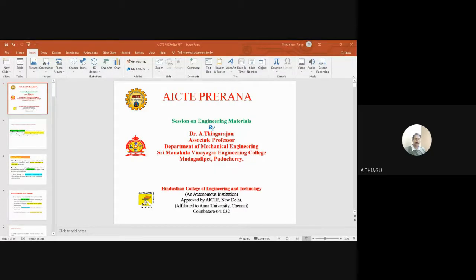Okay, so next, the allotropic forms of different materials are very essential to understand the phase diagram. The first allotropic form of the metal is alpha iron. The name is called ferrite. This ferrite symbol will be alpha. The structure of the metal is body centered cubic structure.